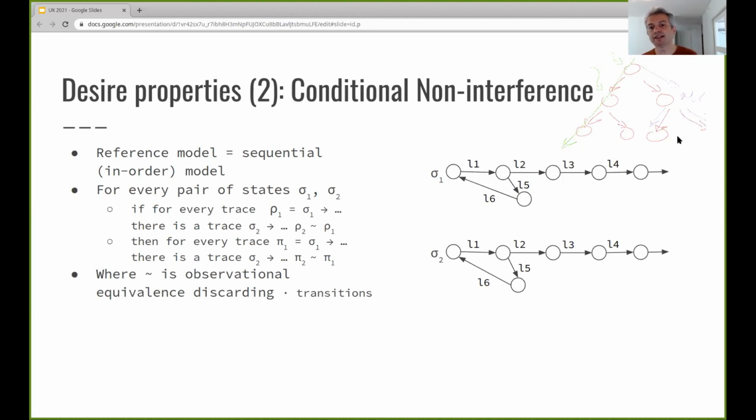They show that it's enough to look at what happens when you always mispredict. You can skip the case where you correctly predict, and this is enough to over-approximate the leakage that happens with prediction. The reason is that if the pipeline mispredicts in this case, when it rolls back it will also execute this branch later on, for the correct prediction. So there is no need to check the condition where you only mispredict two branches. You can just check the one where you mispredict all branches.